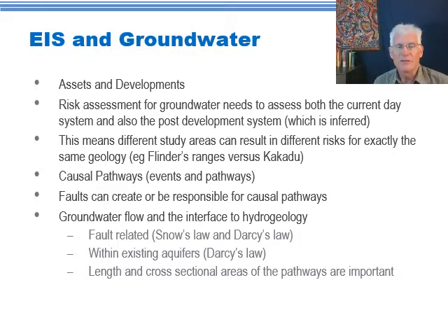Then finally, one thing that we need to do as we're working through all these problems is figure out the length and cross-sectional area of the pathways where the water can flow. And then we need to know a lot about the characteristics. So what's the fracture density, or what's the permeability? What's the porosity? How much water can pass through these and how fast given a certain assumed pressure difference? Okay, so that's kind of the map of where we're going.